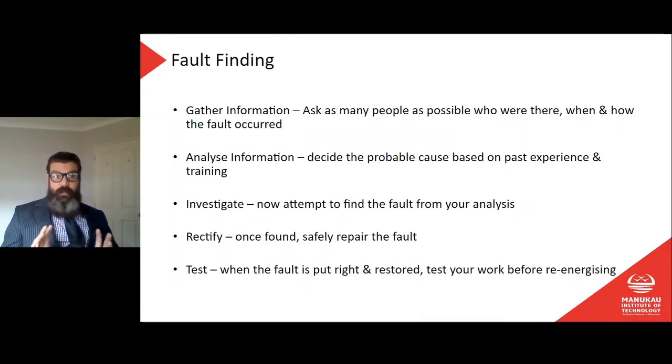It could seriously be anything. It would range from your basic faults where the hoses are worn, or the hose is split. Someone dropped the nozzle and it broke. Mechanical things like that. Keypad's not working on the pump. The lights aren't working in the pump. To the pump's not operating. We pick the pump up, it doesn't work, or I've turned it on in the morning and the display doesn't show up, and something like that. So there's a vast variability in the types of faults.